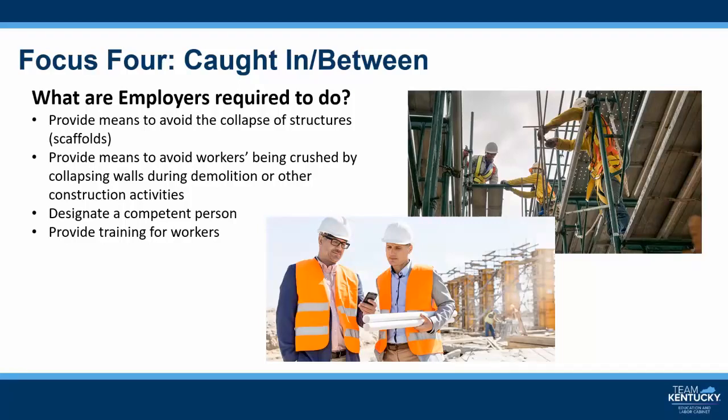Cinder blocks or other similar materials should not be used to support a scaffold because they could be crushed. OSHA standards require that scaffolds can only be erected, moved, dismantled, or altered under the supervision of a competent person. The competent person selects and directs the workers who erect the scaffold. These workers must be trained by a competent person on correct procedures and hazards of scaffold erection.